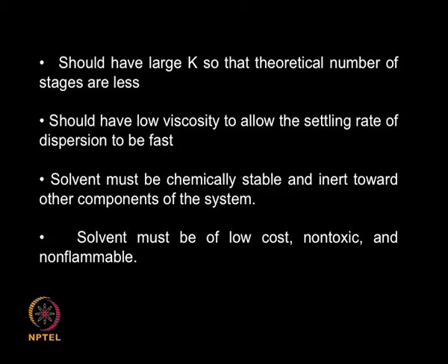Viscosity, if the viscosity is very large, then your settling is going to take a much longer time. So, I should have low viscosity. Now, the solvent must be chemically stable. You do not want a solvent which is not chemically stable, it may start reacting with some of the solute molecules or feed molecules.